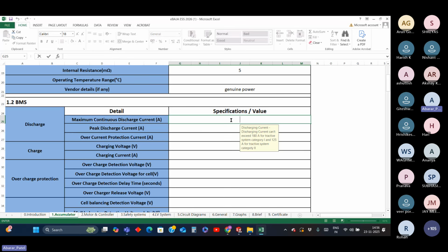You can go lower than the limits, no problem, but you can't exceed them. If you are found exceeding these limits, that might lead to disqualification or some other action against your team. So make sure that you are limiting the power through currents, you are using an appropriate fuse, and your cutoffs for discharge as well as currents are within the specified limit.